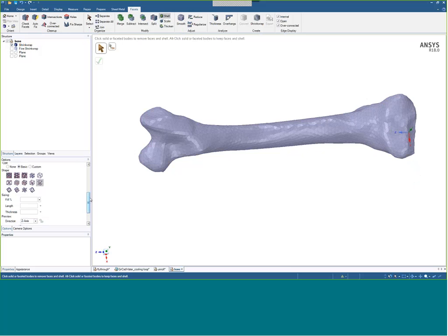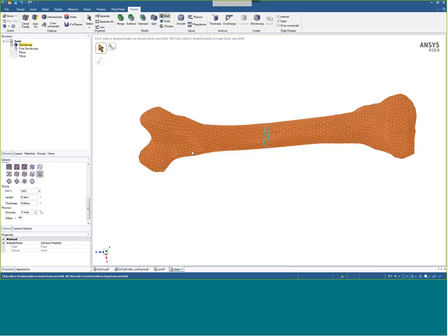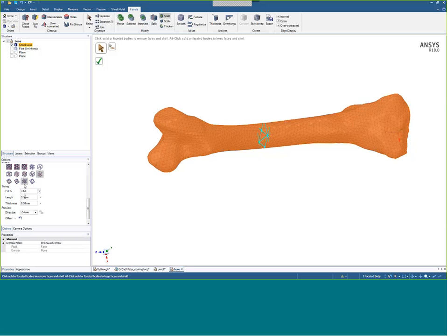But if we also want to see what this looks like, we can actually create our own infill on this model. And one of the other things we've added, which is unique in this release, is we don't assume what values are going to be there. Based on what you select on your model, it automatically sizes a length and a thickness that it thinks is a generally appropriate size for your model. So instead of having things be wildly too large or small to start with, it will auto-size to get you a rough approximation. But as with anything, obviously if you want to change the size or the shape of any of these values, you can obviously type your own in.